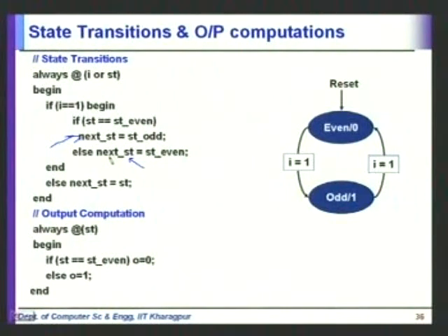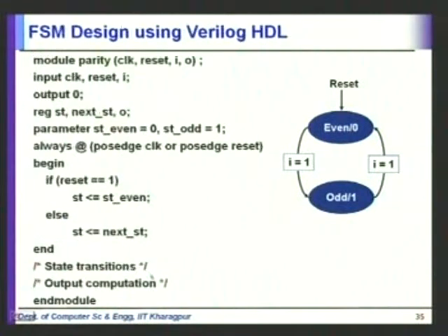In a finite state machine, you have received another 1 in this clock cycle. So this next ST tells you which is the next state, but that next state will become the state of the system at the next positive edge of the clock. Now these are blocking assignment statements. These are not non-blocking. But in the previous slide, we have these as non-blocking assignment, just to make sure that this assignment of the next state that has changed right now will be used in the next clock edge. This non-blocking assignment will use the previous one.